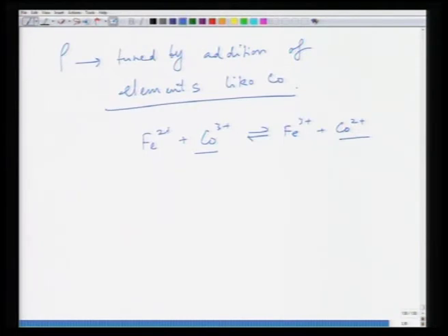So, basically any Fe2+ which was in the material will convert back to Fe3+. Similarly, presence of Ni3+ is also discouraged because of cobalt. So Ni3+ plus Co2+ will be Co3+ plus Ni2+. So in the presence of cobalt, Ni prefers to be in the 2+ state, and the iron 3+ state is preferred, and these factors increase the resistivity of this material.